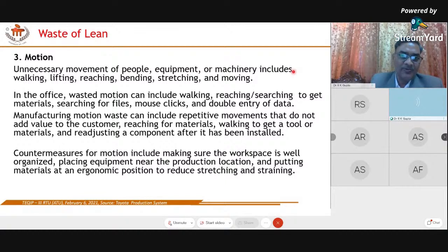So why do we make the composite part concept? This composite part for a given family is a hypothetical part. We made it a hypothetical part that includes all design and manufacturing attributes of the family. It means not all these features are present in every product of the family, but some of the features are available in one part, other features are available in another part. But whatever the features in the family, whether the design features or the manufacturing attributes, we made it one composite part. So an individual part in the family will have some of the features of the family, but not all of them.